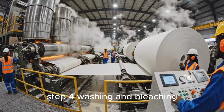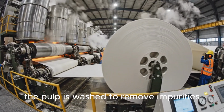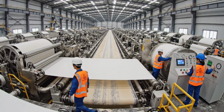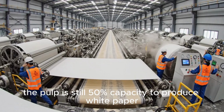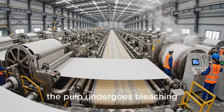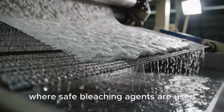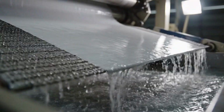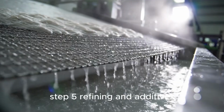Step 4. Washing and bleaching. The pulp is washed to remove impurities, chemicals, and the dissolved lignin. After washing, the pulp may still appear brown in color. To produce white paper, the pulp undergoes bleaching, where safe bleaching agents are used to improve brightness without damaging fibers.